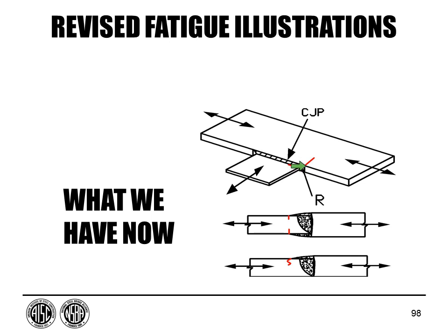Now unfortunately AASHTO wouldn't print this in color, so these lines are black in the specification. But they illustrate the direction of the crack. And you'll notice one important thing. This crack is perpendicular to the direction of the stress range, and that will always be the case. The cracking that you're considering would be perpendicular to this stress range because that's how cracks grow in tension.